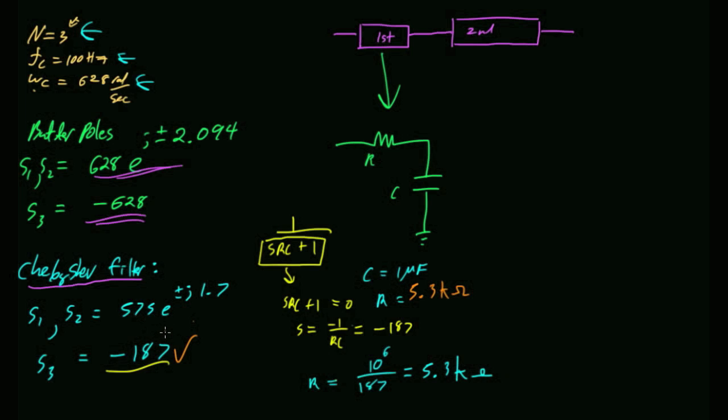How can I get complex poles? I've got 2 choices. Choice number 1 is to do an RLC circuit. But as I tried to make the case on Wednesday, although mathematically that works out, from a practical standpoint it leaves a lot to be desired because it's very hard to daisy chain those circuits together without an op-amp in between them. If you daisy chain them together without an op-amp, then one circuit will affect the performance of the other circuit and all your poles will not be where you think they are. So instead, we tend to follow some other circuit topologies that have better performance.